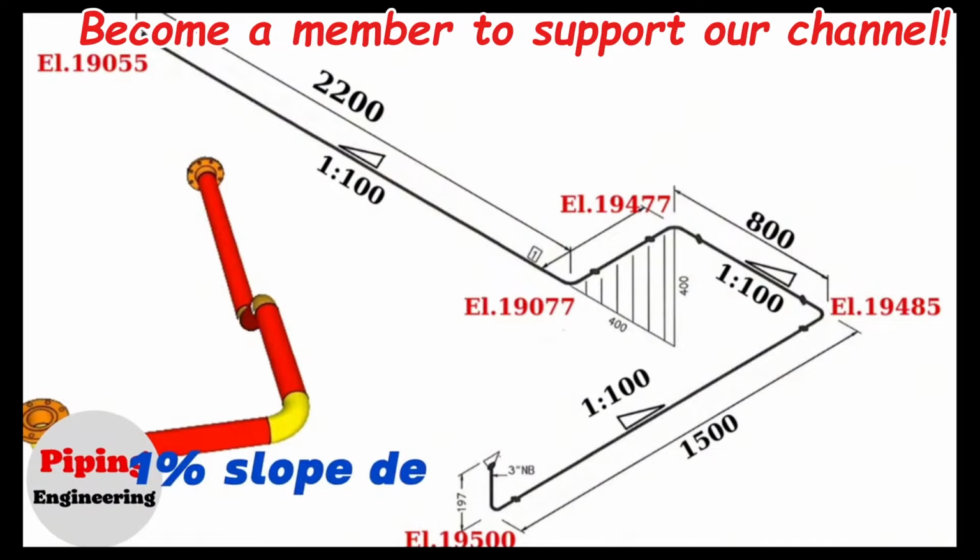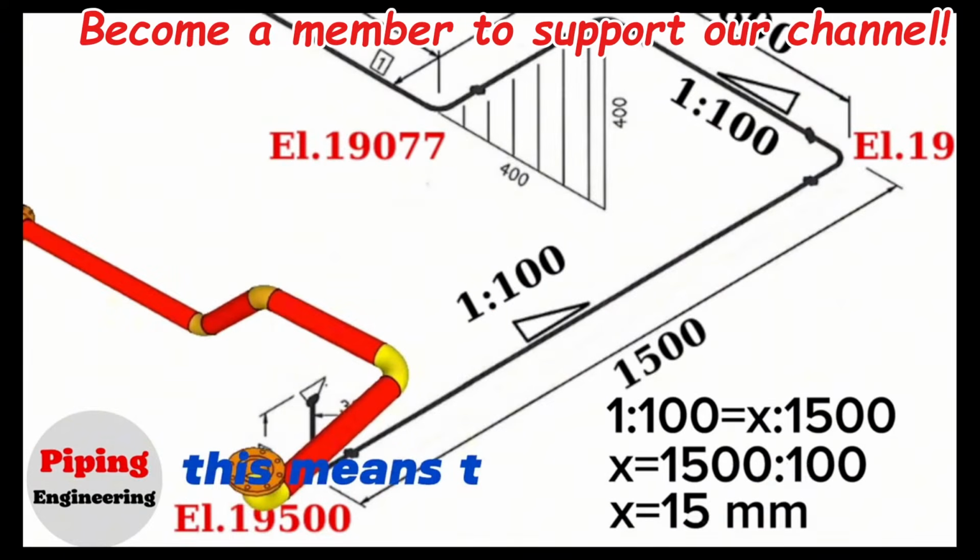Let's calculate with the slope ratio in this example. In this pipe isometric drawing, the slope at a horizontal distance of 1500 is expressed as a ratio of 1 to 100. 1 to 100 ratio equals x to 1500 ratio. Continue, x equals 1500 divided by 100. Continue the calculation and we find x equals 15 millimeters. This means that the 1500 millimeter long pipeline falls 15 millimeters down at the other end with a slope of 1 to 100 ratio.